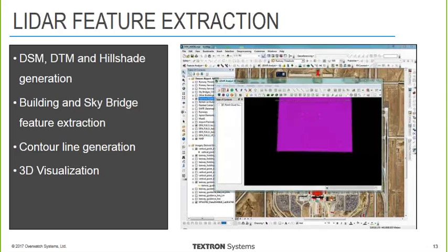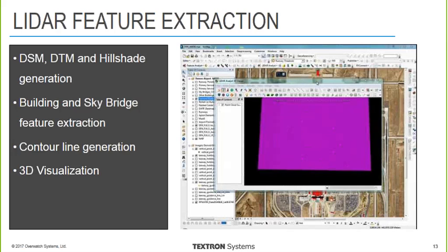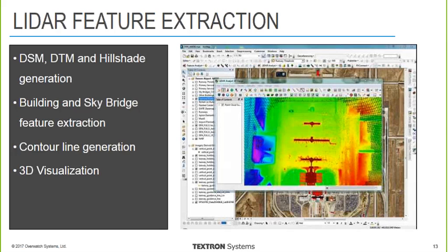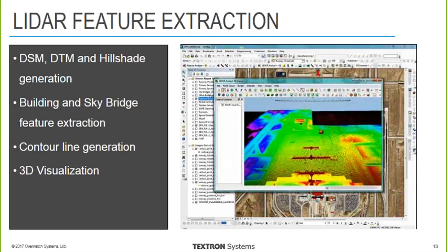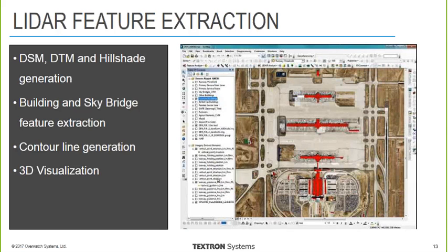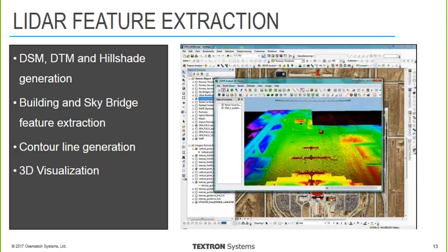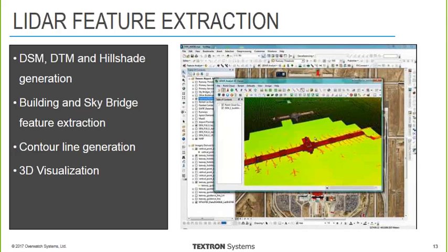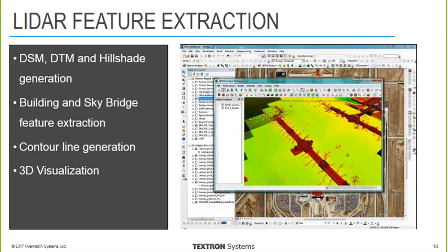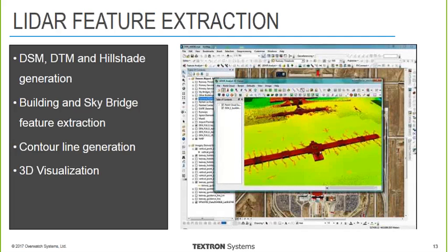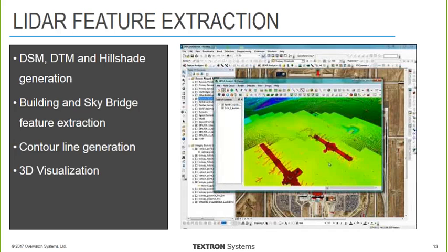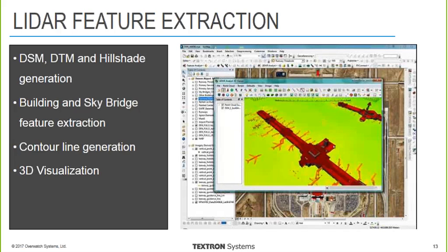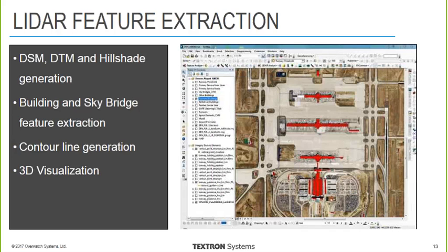And so from there, we probably visualize in 3D. LiDAR Analyst has a robust 3D viewer that will basically visualize and analyze up to 1 billion points. There's our point cloud. Now we can just right-click. We can add that building layer right into the point cloud, and there we go. So as we work through the data set, we can just add everything into 3D. We can cross-check this way. The 3D viewer can output to Google Earth, PDF, PowerPoint, a number of different formats, including OpenFly. So we're now working in a 2- and 3-dimensional environment, if you will.